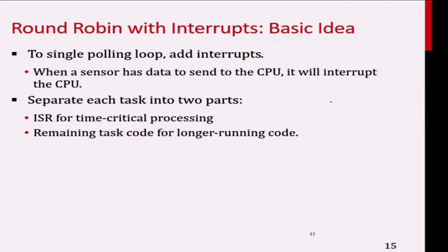So what you are going to do in the lab is your GPIO interrupt. In your lab, you're going to be connecting a switch. I can't remember active high or low, and you're going to write an interrupt service routine for it. So whenever I press the switch, I will jump to the interrupt service routine. And of course, this is an external interrupt. You can also have internal interrupts, which are peripherals within the microcontroller. Things like your timer, your serial port, your ADC, a PWM. So all these are your internal peripheral blocks of your microcontroller, and these blocks can also generate interrupts for you.